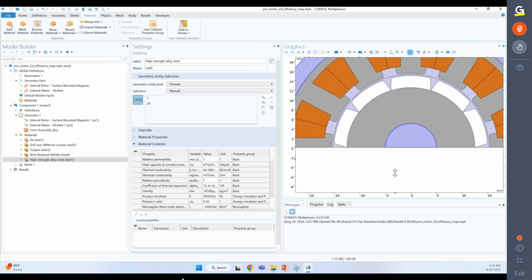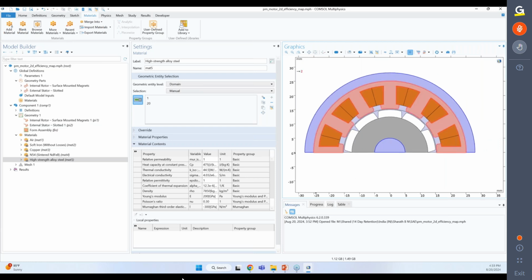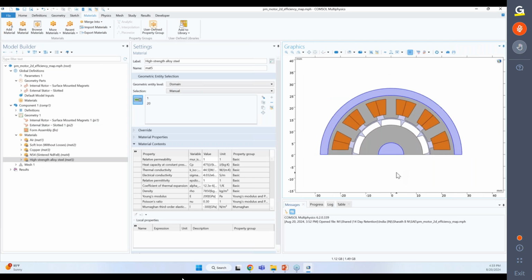You might be seeing that we only have a half sector geometry. Initially in one of the slides, I was referring to how you can implement the sector geometry to reduce the computational load on your system. This is a live example that we have. We are only considering the half sector of your entire 360 model, so we are only considering the 180-degree model.